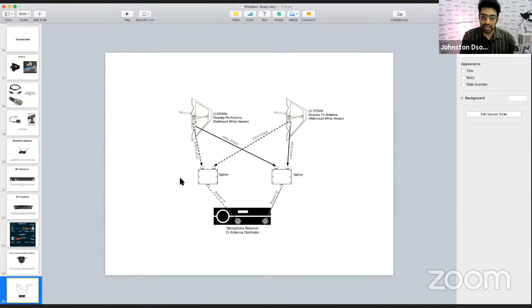So what is happening in this case is, no matter how far the antennas are placed from the transmitter, one of these is always going to catch the RF. There's not going to be any dropout. Did you understand this whole system that they did? So even when you're planning RF, unlike audio where we are concentrating on mixing, when you're planning RF, it requires a lot of planning and proper laying out of where you're going to put your antennas and where you're going to put your transmitters and how you're going to set the entire system up. You have to also calculate how much signal drop you'll get depending upon how long a cable you're using. Is that clear?